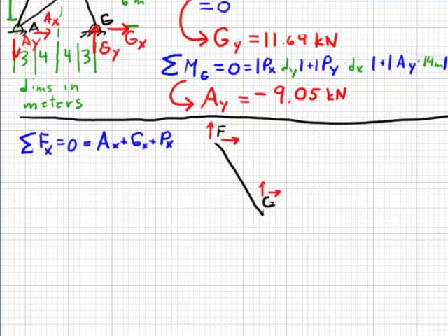This is what makes it a strut, or if it's in tension, a tie, but we'll just refer to it as a strut at this point. Because of this setup, 2 pins only. If it were 3 locations, this would be a beam and bending possibly, but just because it has 2 pins, it's a strut.